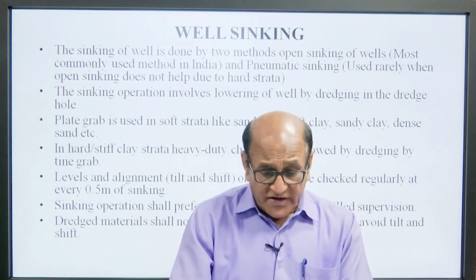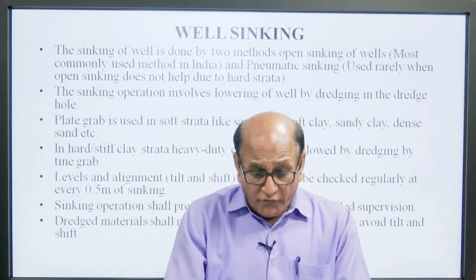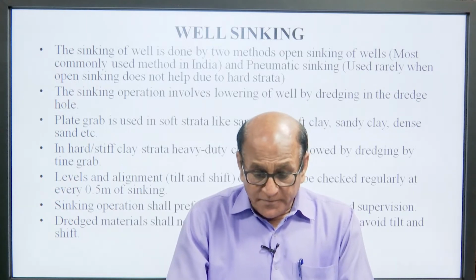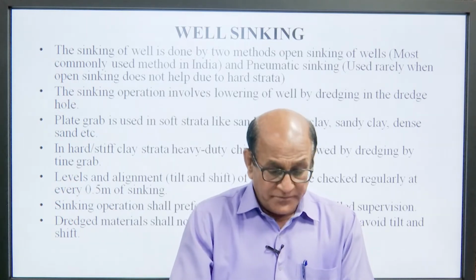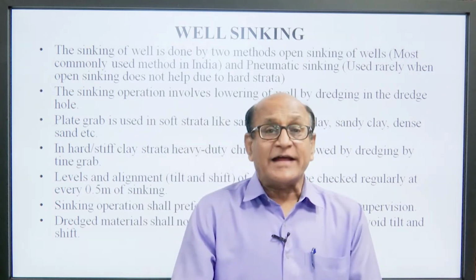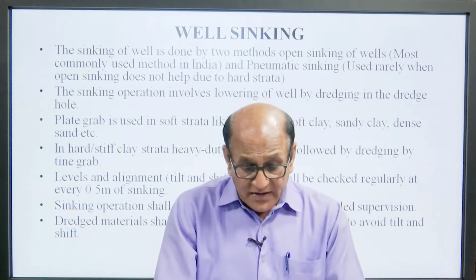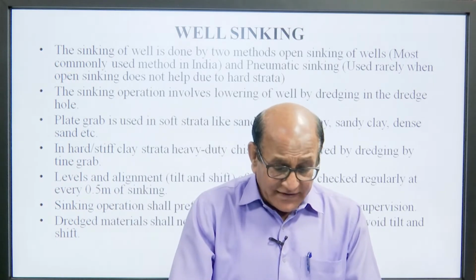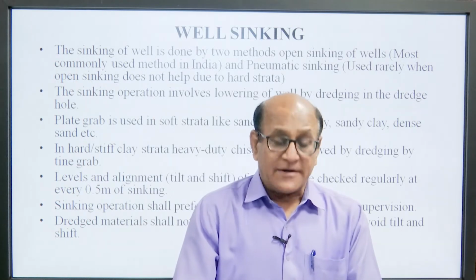The sinking operation involves lowering of the well by dredging in the dredge hole. Grab is used in soft strata like sand, silt, soft clay, sandy clay, dense sand, etc.